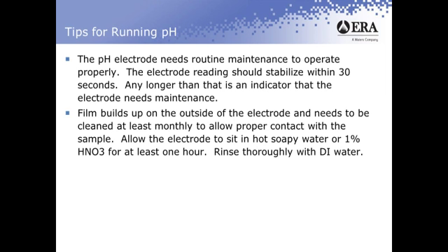What happens is when the film builds up on the outside of these electrodes, you're going to get poor contact, and that's going to increase the amount of time before you get a stable reading. And the more time it takes for that stable reading to happen, the more inaccurate your testing is going to be. So cleaning the film on the outside of those electrodes is actually quite simple.